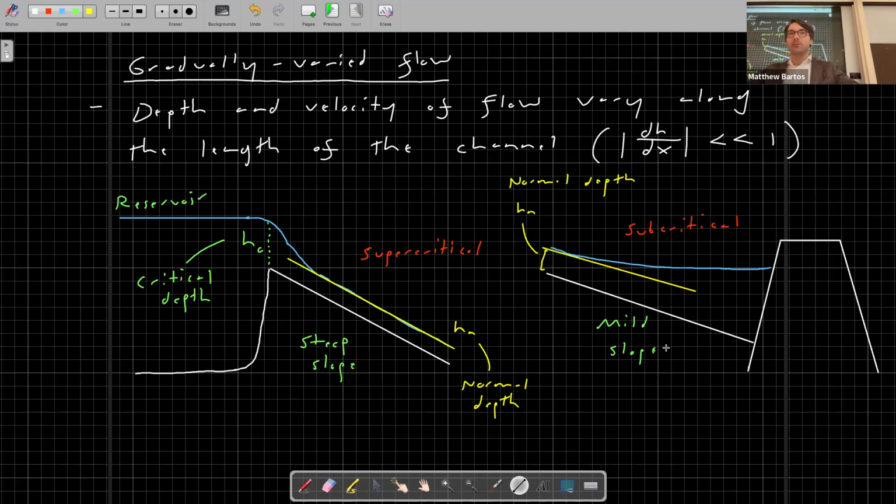So for the first case, as you move downstream, you have a relatively constant slope over a long distance, and it will asymptotically approach that uniform flow depth. Same for the subcritical case, except moving in the upstream direction. Good question. Any other questions on these two examples?